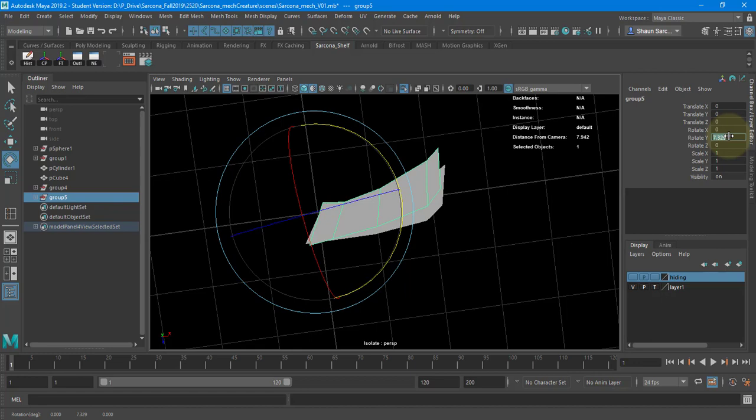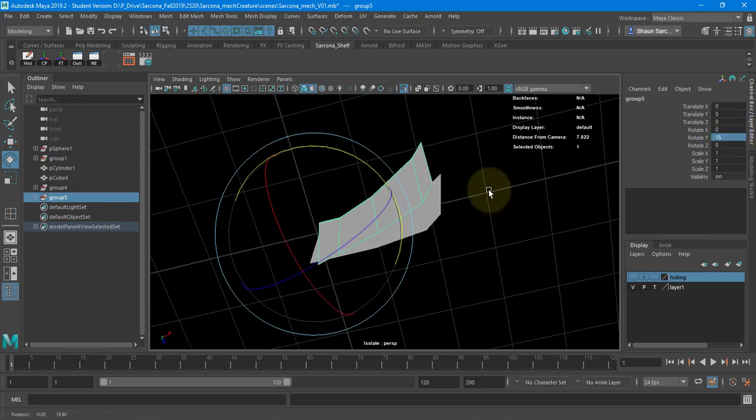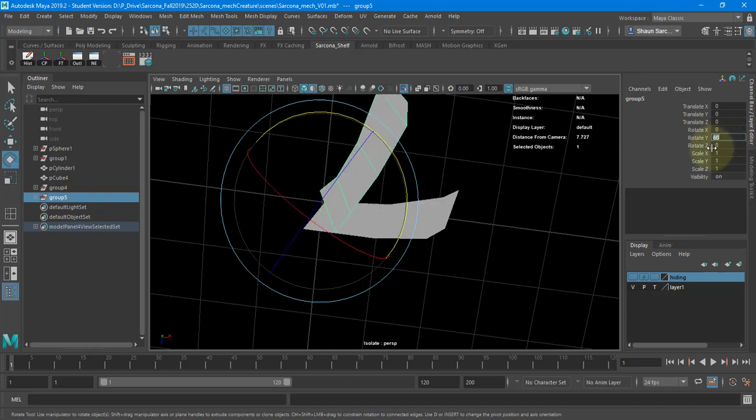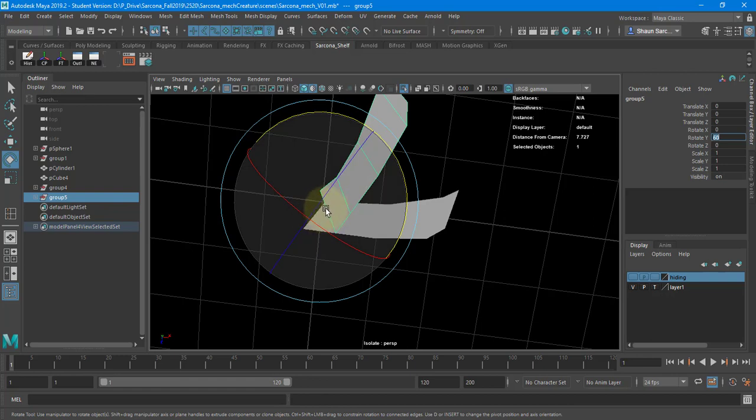360, right? So if I use 7.329, does that evenly go into 360? Probably not. So I need to find some number that will evenly go into 360 without giving me some crazy values. So if you don't want to do math on it, 15, 10, those are typically good numbers. 20 would also go. The smaller this number is, the more of these iris blades I'm going to get. Okay? So if I went to 60, that would give me less iris blades, but it would still work. Or it should still work as long as I have a smaller opening.